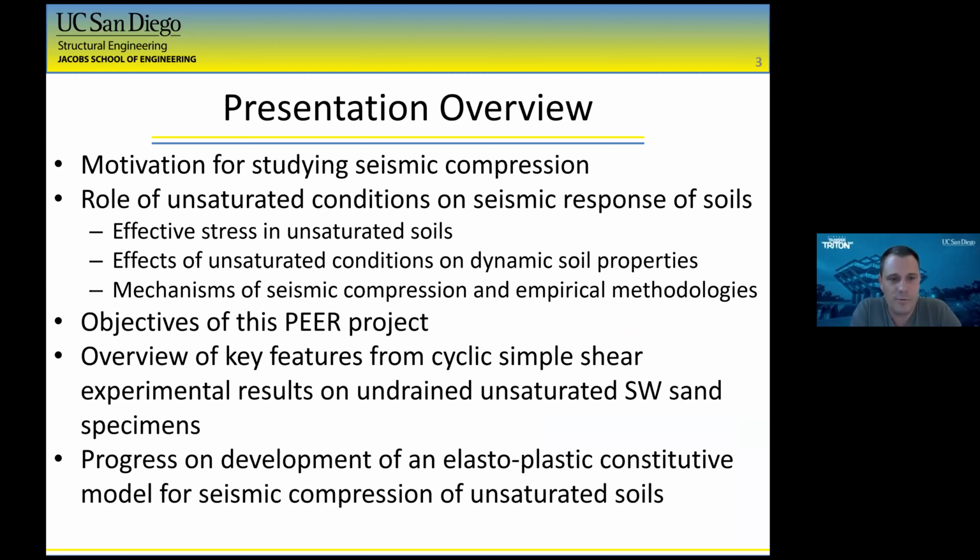Then I'll go over the objectives of this particular PEER project, show some of the key features that we observed from our cyclic simple shear tests, and then show some of the progress on the development of an elastoplastic constitutive model for the seismic compression. We're extending the UBC sand model to unsaturated conditions, and we're adding some hydraulic coupling features into that.